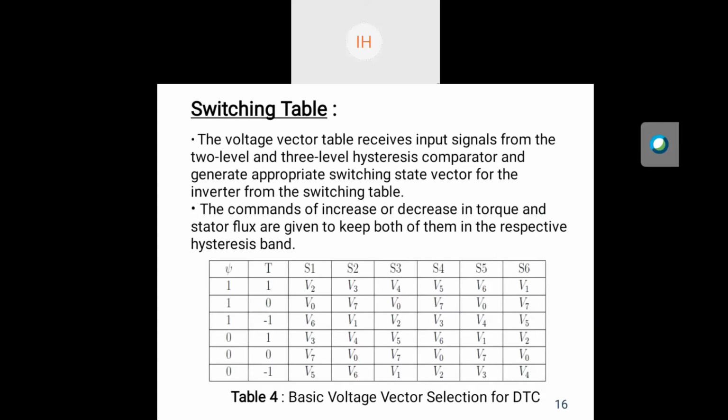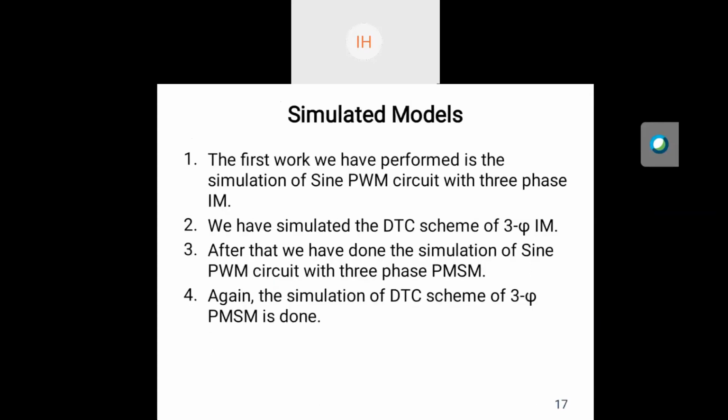So, simulated models. Here we have simulated a sine PWM circuit with an induction motor. We have simulated DTC of a 3-phase induction motor. Also we have simulated SPWM with PMSM and DTC of PMSM.